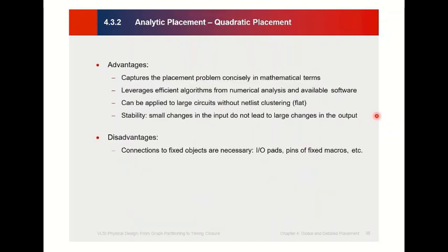This algorithm has the following advantages. Number 1, it captures the placement problem concisely in mathematical terms. Number 2, efficient algorithms from existing numerical analysis and software are available to solve the linear equations, the partial differential equations, to find the location for x and y coordinates.